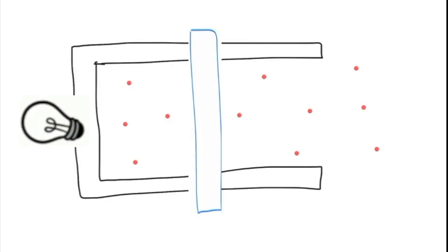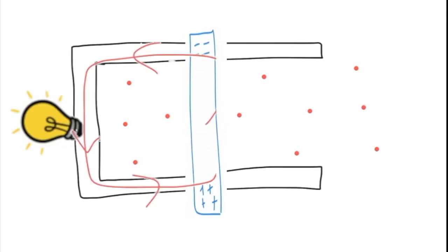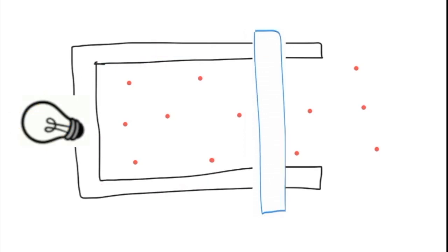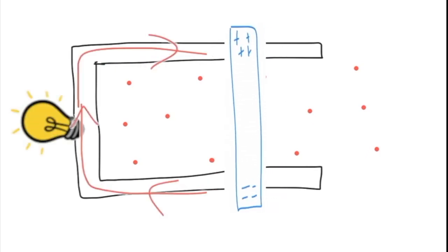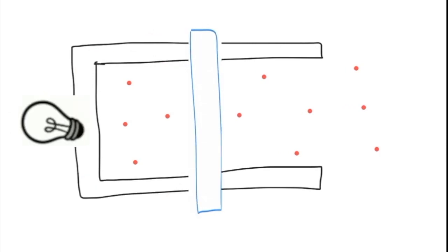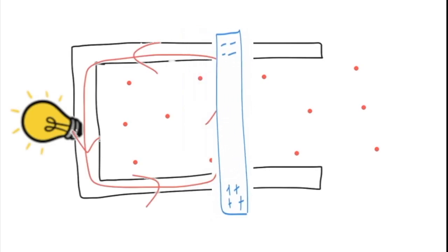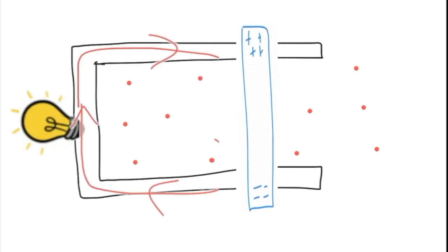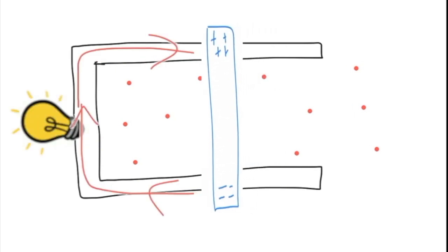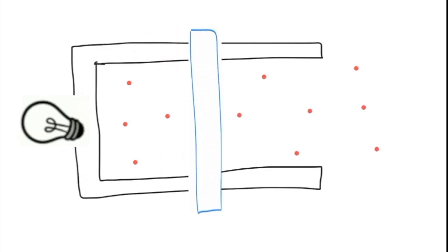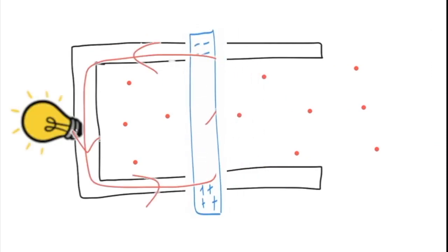Going back to our bar and rails, we can see that if I pull the bar this way, the top of the bar is high and the electrons would go counterclockwise. If I pull the bar this way, the bottom of the bar is high and the electrons go clockwise. Suppose I pull the bar forward for 5 seconds, and then pull the bar backwards for 5 seconds. That would make a counterclockwise current for 5 seconds, followed by a clockwise current for 5 seconds. The faster I cycle through direction changes, the more often the current turns around.